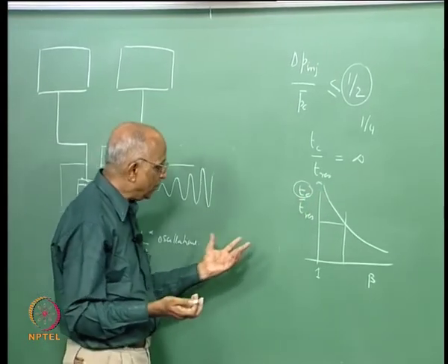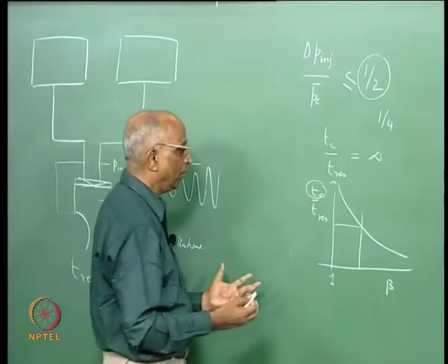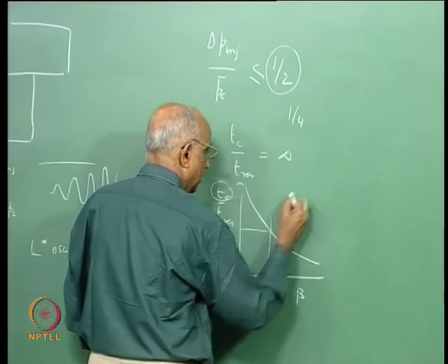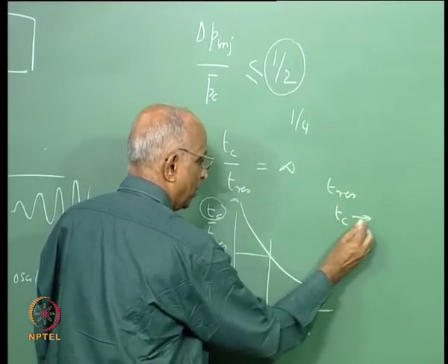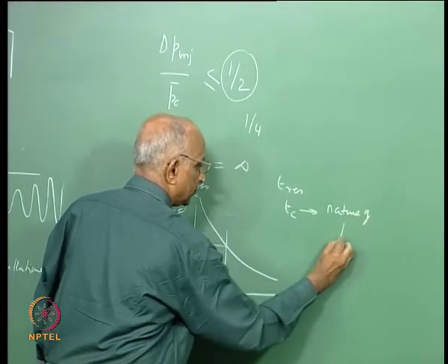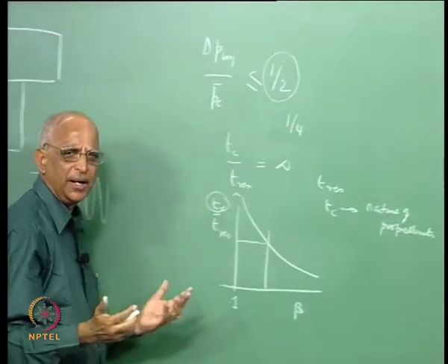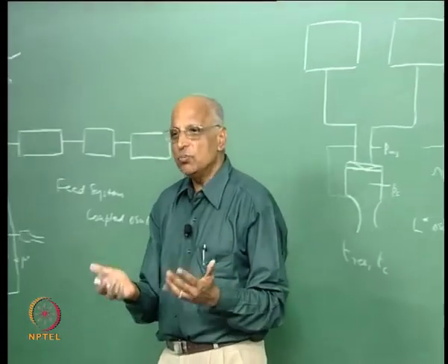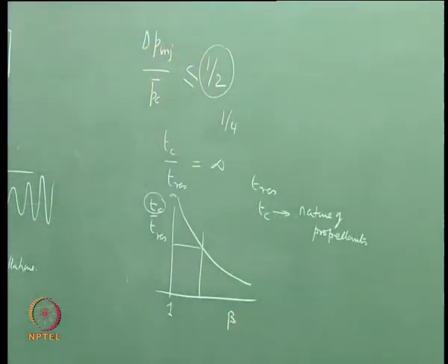Therefore, the feed coupled oscillations or L star oscillations are a function, we must remember, of not only the residence time but also the value of Tc. It is because it is a function of Tc that it becomes a nature of propellants. Maybe if I have propellants which are sluggish like aniline and red fuming nitric acid, it is more susceptible because they have a larger delay. I think this is all what I will do in these feed coupled oscillations with respect to liquid propellant rockets.